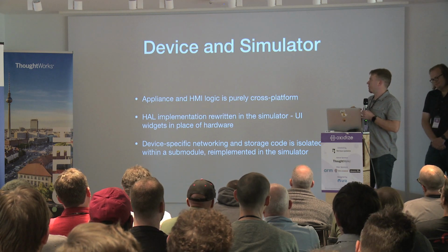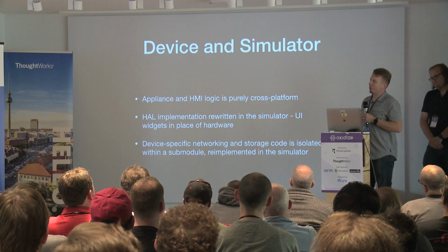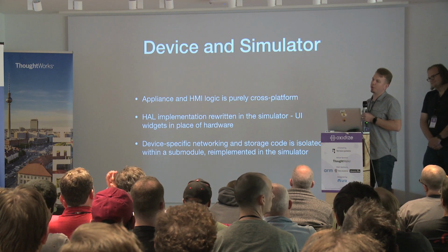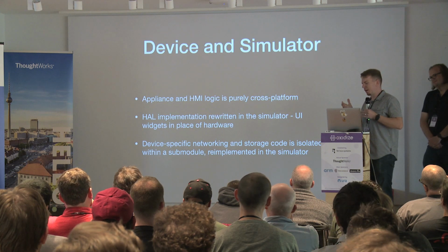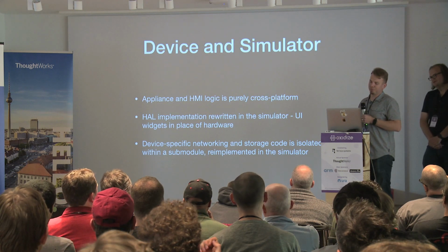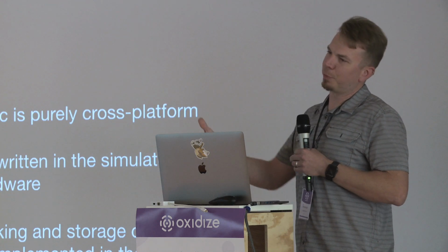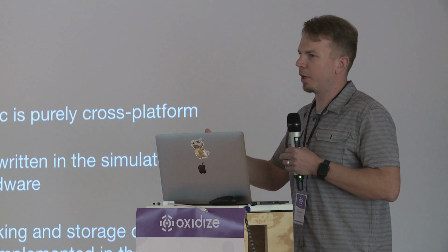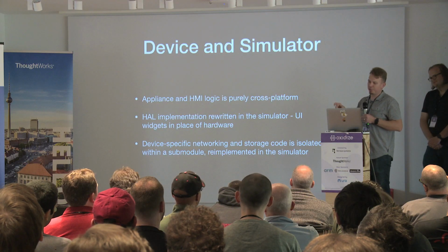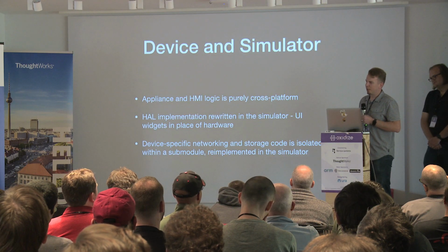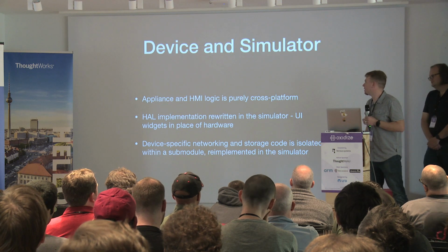As we were building this, the key topic here is that we wanted to build a simulator for our hardware. The hardware that we're using, I have to plug in 3 USB cables to really use it completely, because there's one for power, there's one for the debugger, and then there's one for USB to UART for the console. And it's not very convenient.